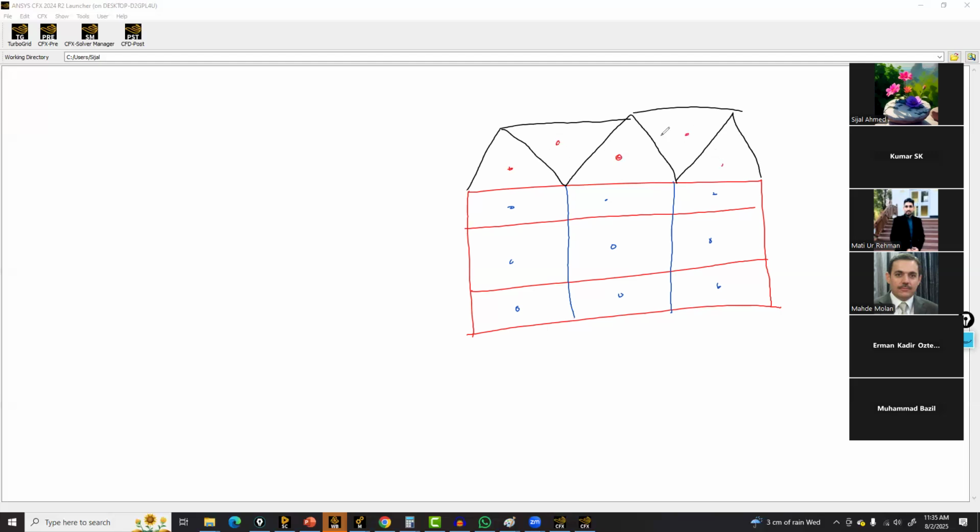Okay. So what will happen with the CFX is that it will be creating the mesh from these nodes. So now the element that is generated by the shape functions inside the CFX is this element. So instead of having the tetra and the hexa elements, this is going to be the polyhedra. Okay, and this is the reason that the CFX does not like the polyhedra elements.